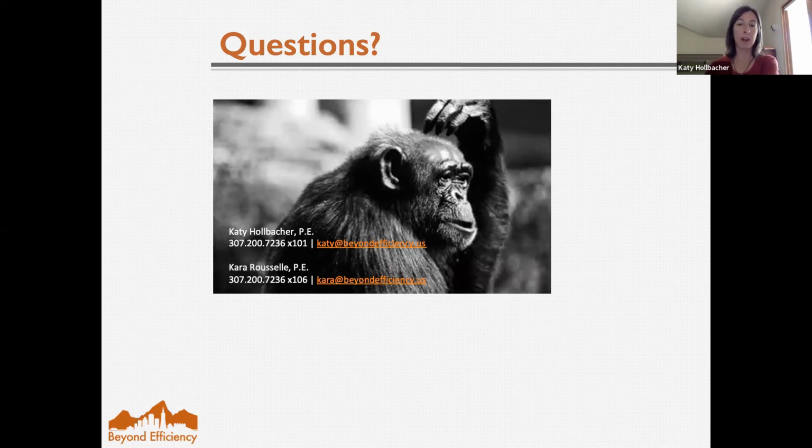Presumably you want the log finish on the inside and outside, so you probably aren't going to want to add a layer of insulation. I think some air tightness improvements are always available, depending on what's accessible and how many improvements you might need to make, or be able to make. And after that, even if you're not upgrading the envelope very much, heat pumps are just inherently more efficient.